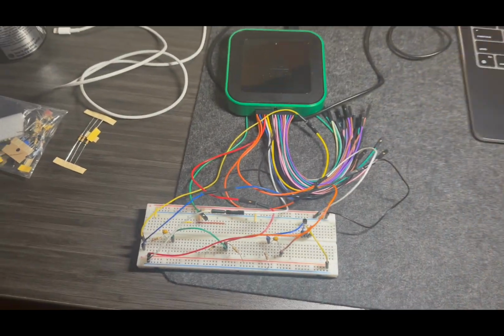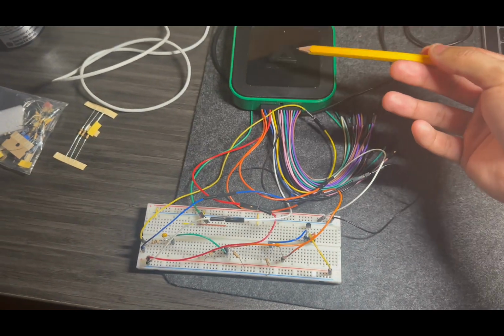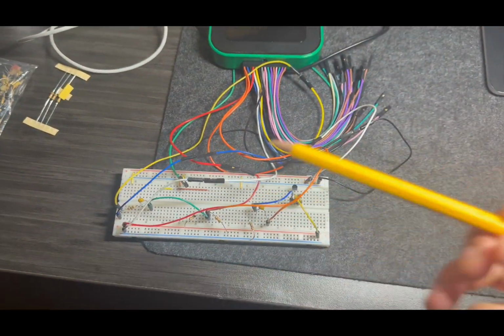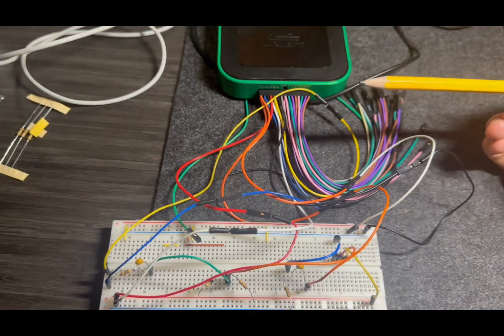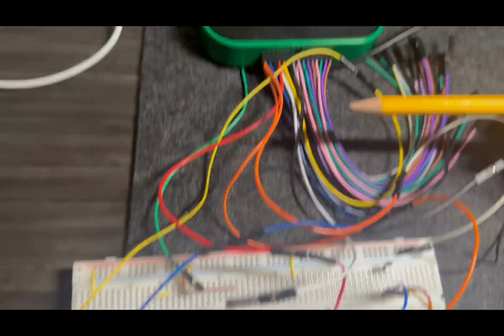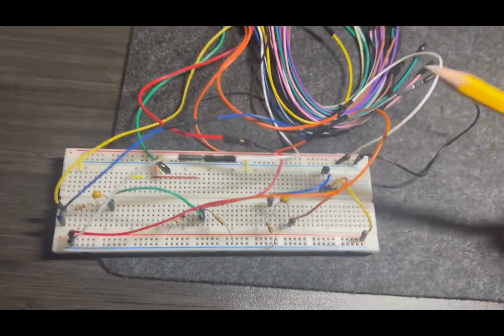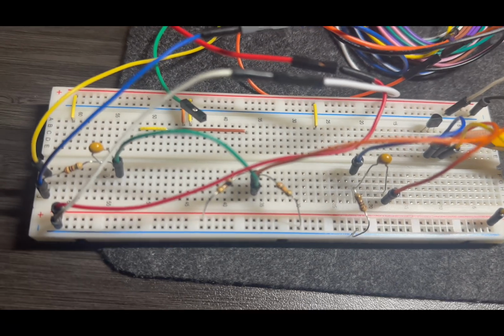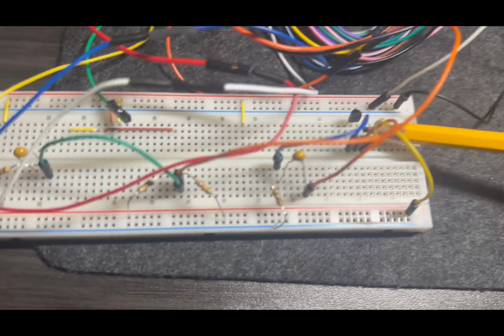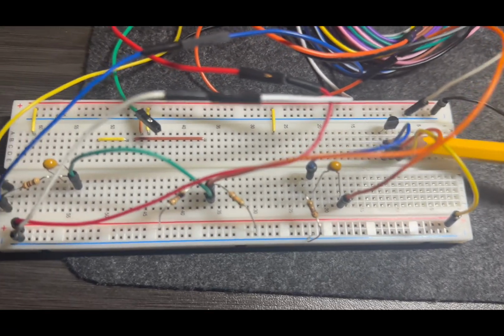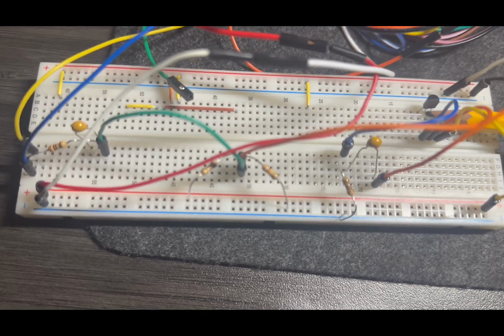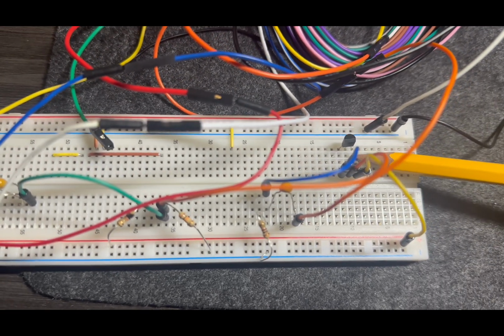So we'll get right into the real circuit. We have the AD3 feeding into the actual breadboard. This supplies our voltages, acts as our waveform generator, and does all the measurements. Right here we have the 2N3904 transistor. We have at the very left the emitter, then the base, and then the collector.